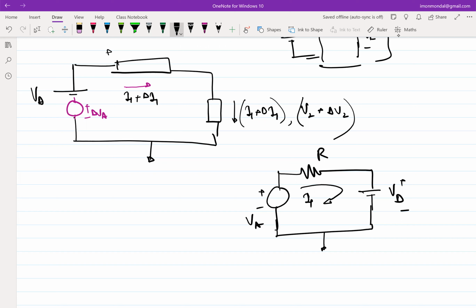No, right? So similarly, this argument, I mean, this is obviously not a rigorous proof. You can prove it rigorously, but the argument essentially is that the substitution theorem tells you that you can replace any element in the network with either a voltage source or a current source corresponding to the original voltage or the original current before you did the replacement, and nothing else will change in the network. That should also be very intuitive, right?